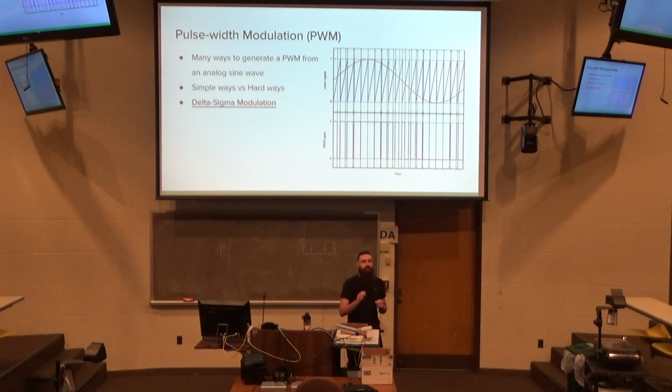Your USB transmits a digital signal at a specific voltage. You can also do it analog by changing the voltage. What I mean by that is, you see the PWM signal, 1 and 0. You can change how high the 1 is if you wanted to do it in analog. That'll be important in a moment when we look at how the Class D amplifier works. I just want to make sure that we address that.